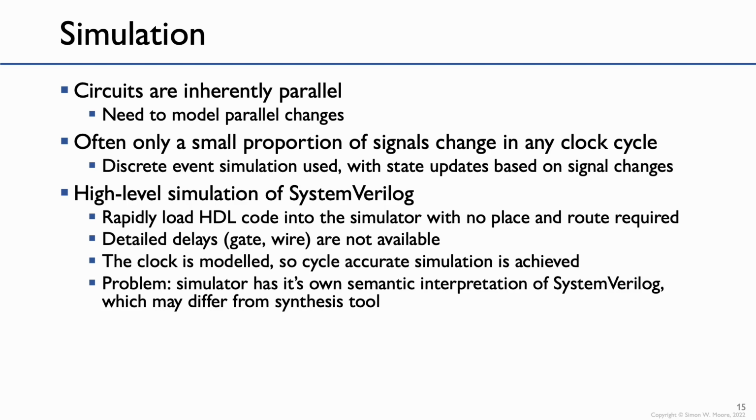So in industry, people often do high-level SystemVerilog simulations to begin with, and then they will synthesize the design through to gates, and then do a gate-level simulation to check that the gate-level version matches the abstract version. Actually, also in industry, they quite often have design styles, and they may avoid particular subsets of the SystemVerilog language which are known to be problematic, where there can be different semantic interpretations.